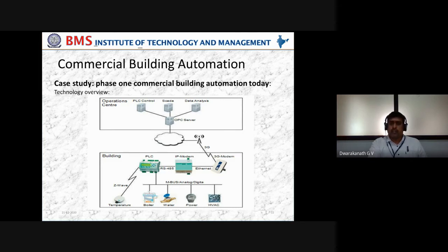And you can see further, this PLC board has been connected with a modem. I can say it's a gateway and a hotspot, especially a hotspot. Usually in our terms, we connect with a hotspot, or you can use any physical connectivity modem, only that, not other things with Ethernet. So through the modem, you can connect to the internet, any hotspot that 3G, 4G is working on. From there, you can transfer the data to the cloud.